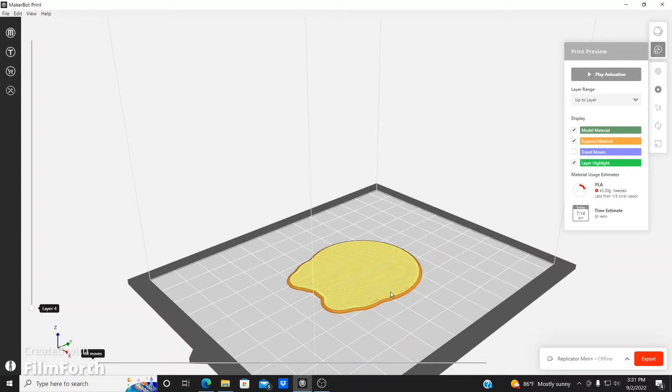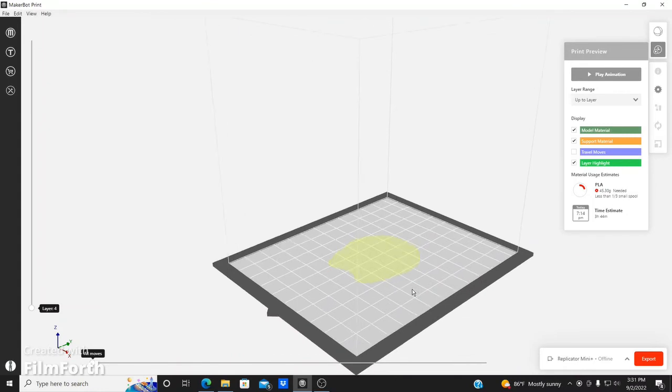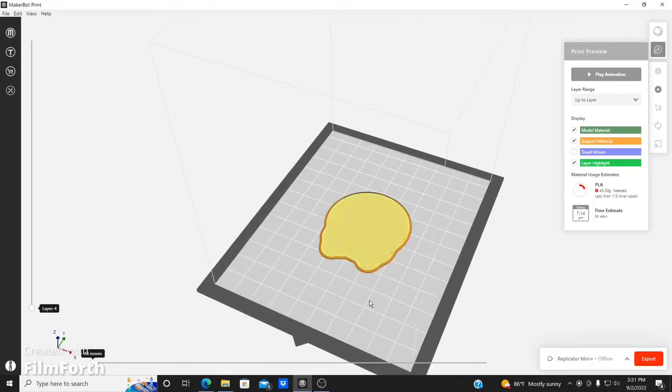Most of the time, if your brim, your raft, or your platform fails, it's because there's no adhesion at the bottom. So either your build plate failed or your nozzle contact onto the build plate was not really tight. But there are ways you can prevent that from happening.